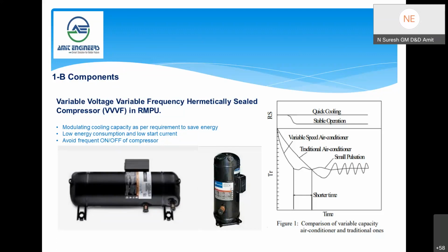Yes, please go ahead. What about regular weekly maintenance? No, for the compressor there is no particular maintenance, sir. There is periodic and preventive maintenance which we will give in the manual. Basically, we have to check that the proper insulations are in place, the terminals are properly fastened, and the terminal covers are properly tightened. These things we have to check on a periodic check.